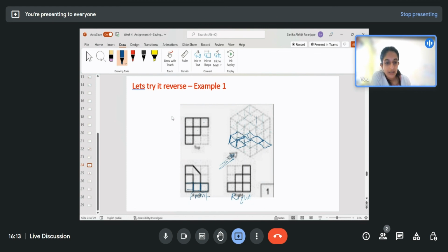Then I again have a block here like this, and this block is this plane that I can see here. Okay, now since I'm able to see a line here also, it means that I have a plane here which is again horizontal but perpendicular to the current viewing plane, which is the plane of the paper. So then there is nothing here. This plane exists in the final drawing.